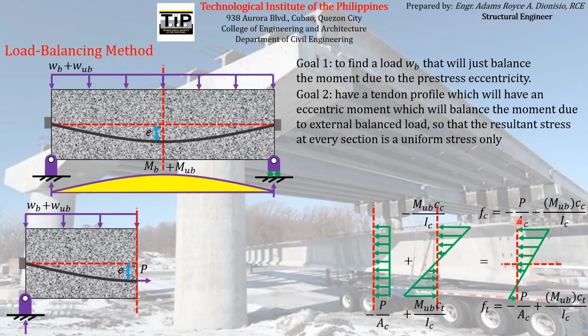So if you get the summation of these flexural stresses here, you can see that the total force acting on this particular concrete section of the concrete element is just a single force C acting at a certain distance from the neutral axis or centroid. So actually that C is just equal to the compressive force we have derived from the C-line method and the basic concept method.